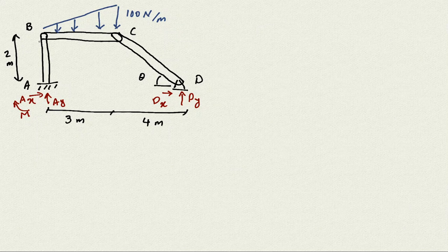Don't get confused, it's not going to be correct for the AB, because on the AB, although we have the force at A and B, we have the moment, and because we have this moment and this moment can be applied anywhere, it's not going to be a two-member force. So AB is not a two-member force, only CD is.